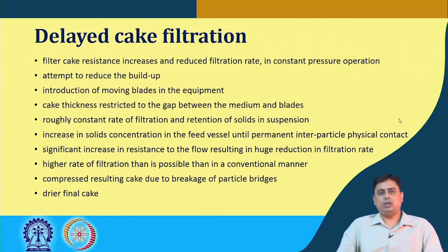That has led to the introduction of moving blades in the equipment near the filter medium, so that they scrape off the cake after a certain thickness has been deposited. The cake thickness is then restricted to the gap depth between the medium and the blade surface. So you give a certain clearance between the blade and the filter media, and that would be the thickness of the cake that you want deposited.